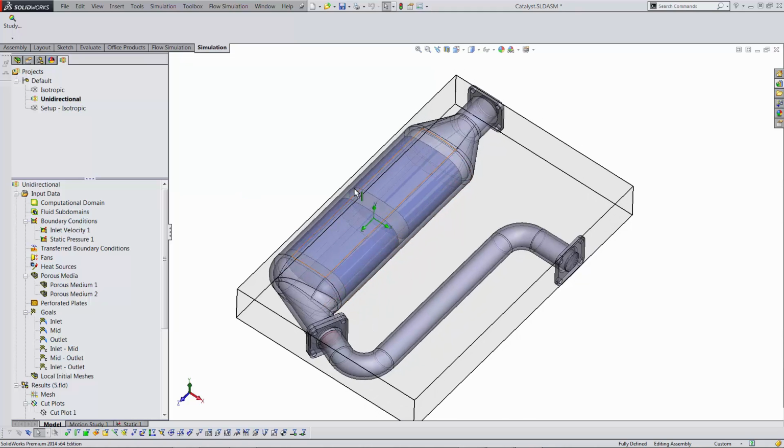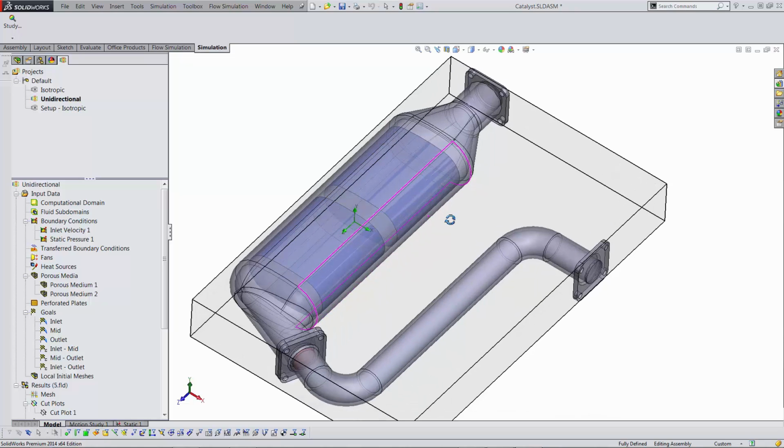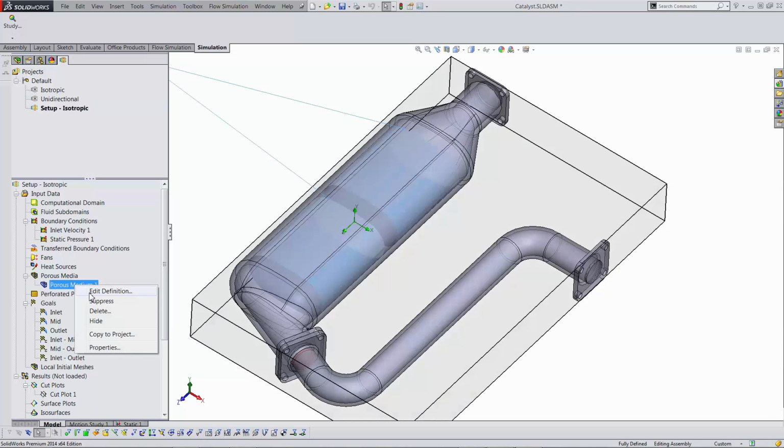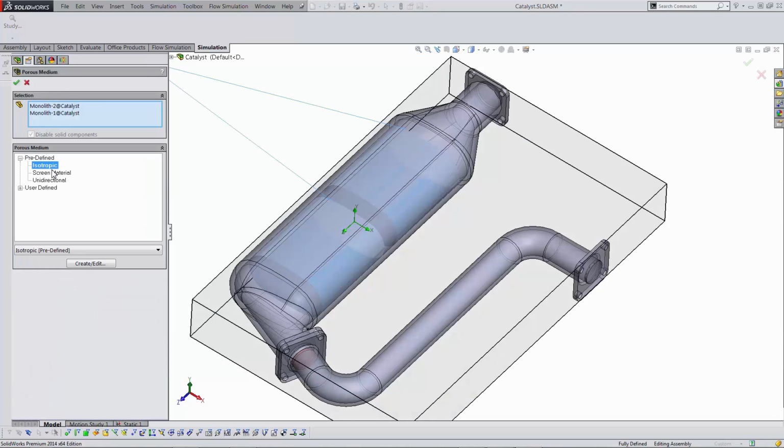Now it's nice to have these two different types and to have these different materials that we set up here in my setup. However, I wouldn't always be able to use these types of materials for a real analysis. I would have to be changing the material type if I wanted different pressure drops. I can't always be relying on changing the length or size of my porous media. So I do have to create these myself.